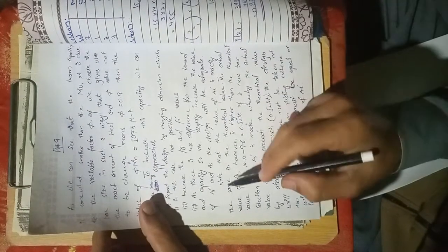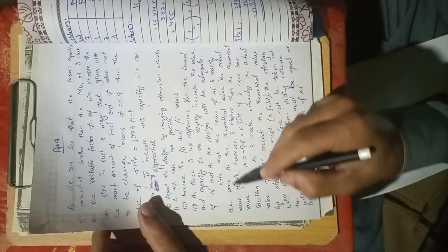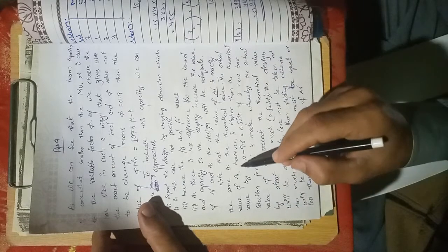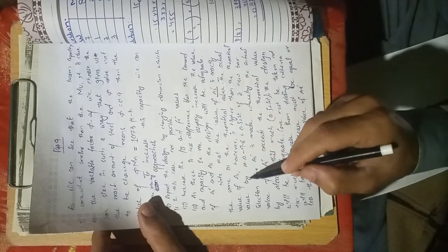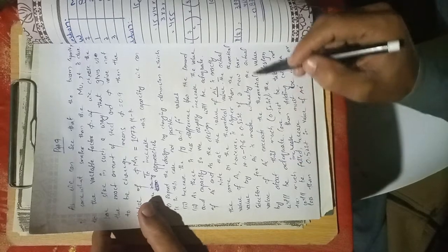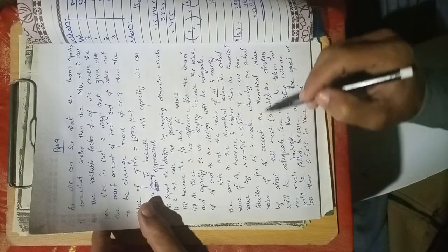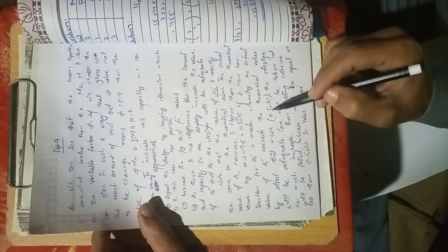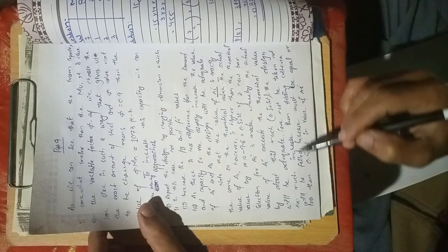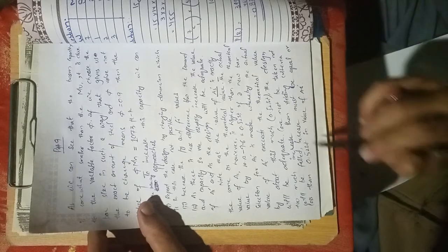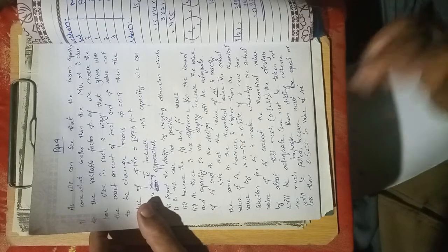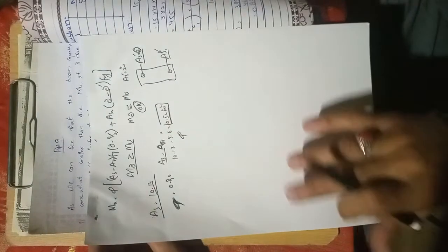Here you can see, note that the value of As prime is exactly the same as the theoretical value. The actual value of As is, however, higher than the theoretical value by this amount. If a new bar selection for As prime is made, whereby the actual value of As prime exceeds the theoretical value by about this much, 0.52, the design will be adequate. Care must be taken not to increase too much, otherwise the yielding criterion will fail, and the increase must be equal to or less than 0.52 square inch. This is the point which I have already discussed with you.